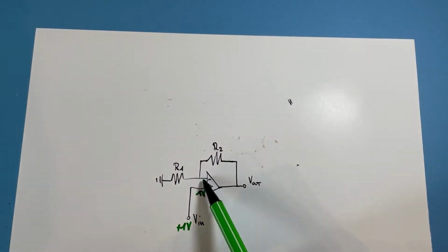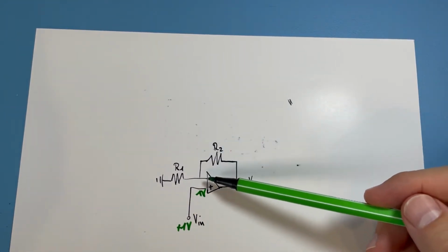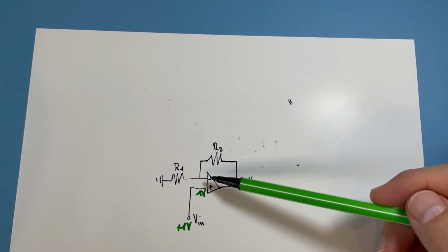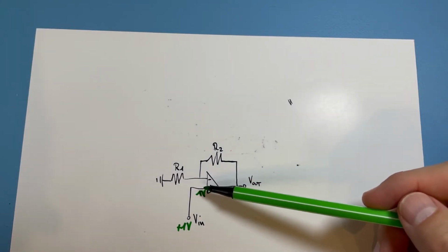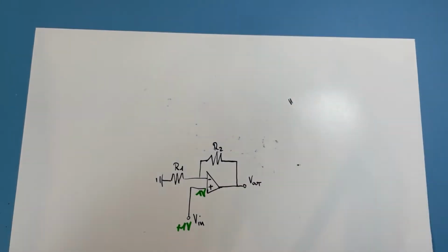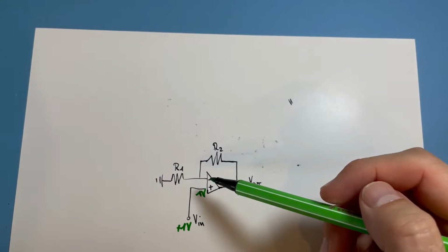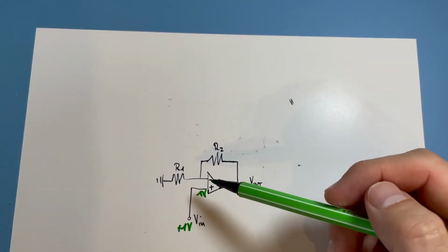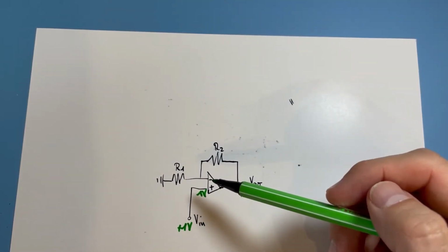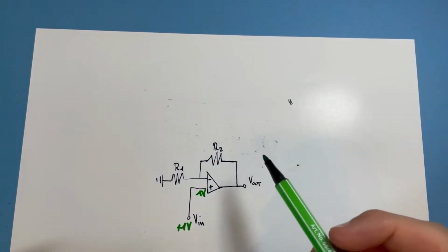And as you know, sometimes the general rule, an operational amplifier, OpAmp, always wants to get the two input terminals to be the same value. Yeah? And it's only then, when the OpAmp has managed to do so, that there is no delta between the input terminals. And then if these two are equal, the OpAmp will stop operating and doing stuff. It would just simply do nothing anymore when the input terminals are equal.